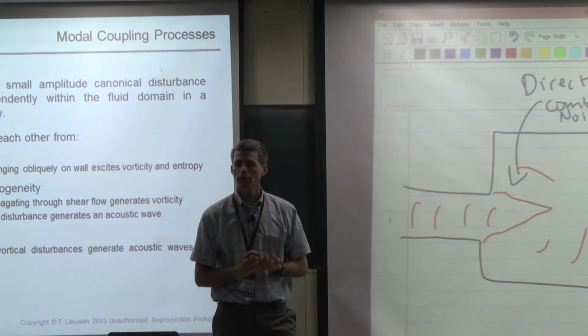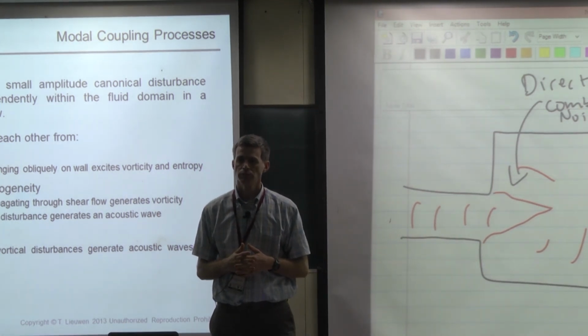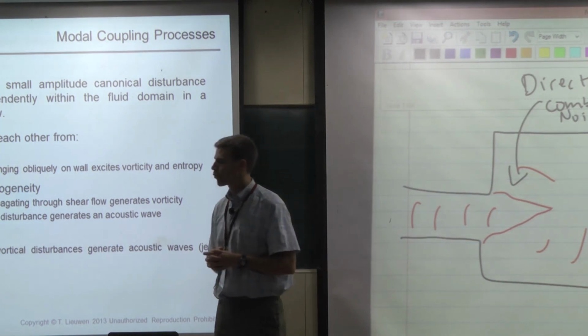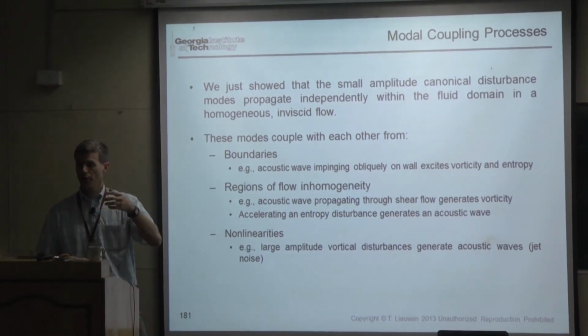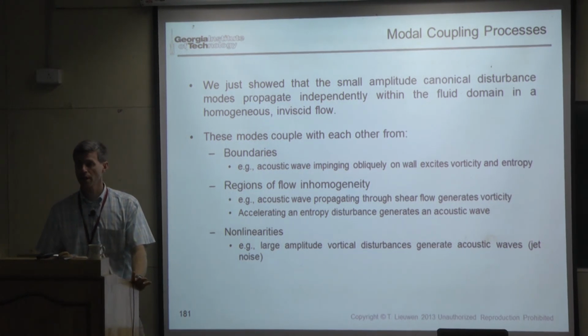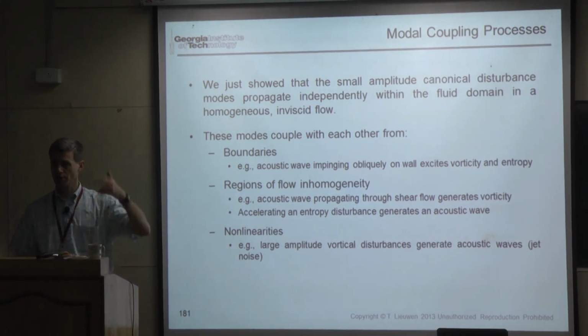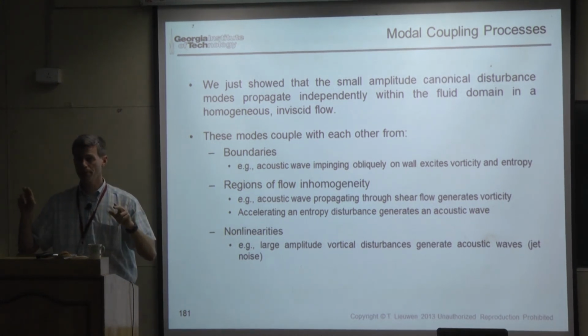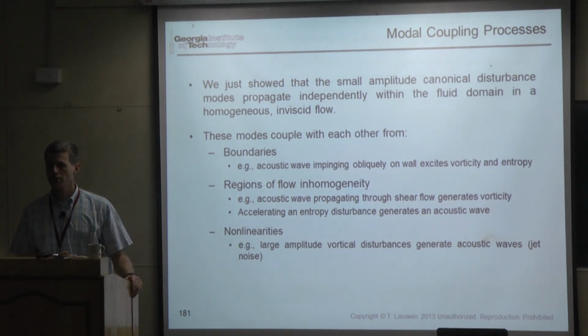Now your Bunsen flame is just a free flame. So the shear layers, when you have that open jet, you have a shear layer, and that shear layer is hydrodynamically unstable, and it will oscillate even without acoustics. So it's impossible to always get rid of acoustics because sound waves will be reflecting. Even if that flame is an open flame, the duct upstream of it is not open. So you always have a little bit of sound waves bouncing around. So you can never totally divorce the problem from acoustic reverberation in your flow section.